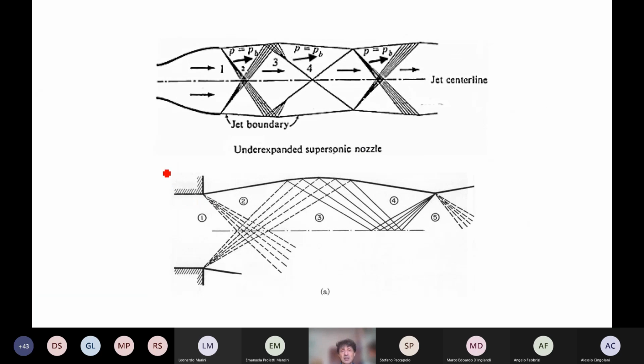So about the underexpanded nozzle, we have drawn some expansion waves like this, and you see that the bottom drawing is something that remains isentropic with compression waves, because it's a planar mild expansion, where you see that the expansion waves reflect as compression waves and reflect again as compression waves, and we never have shocks.